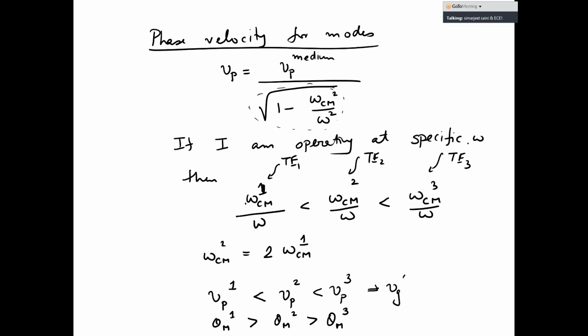The group velocity for the first mode is going to be larger than the group velocity for the second mode, is going to be larger than the group velocity for the third mode. But all those values are going to be different. Each of those modes, each of those solutions, is carrying the information at its own speed. So if I allow three different horses to run through this waveguide, they're going to be unique horses. All those horses are going to take their own time. Each is going to go at different speeds. The first order horse is going to go much faster than the second order horse, is going to go much faster than the third order mode.